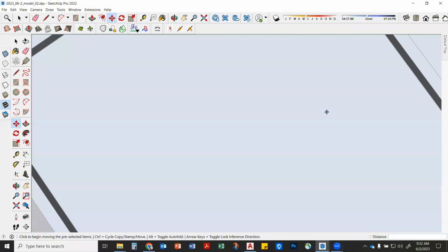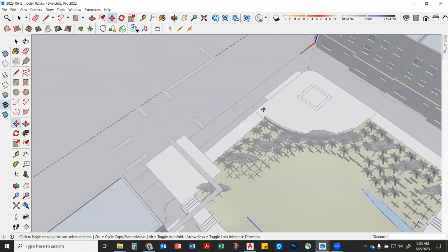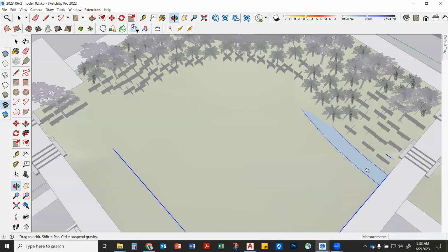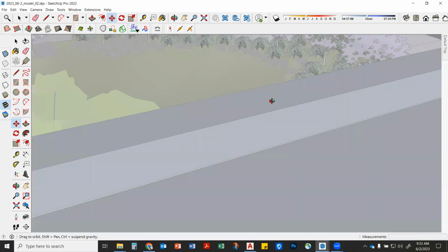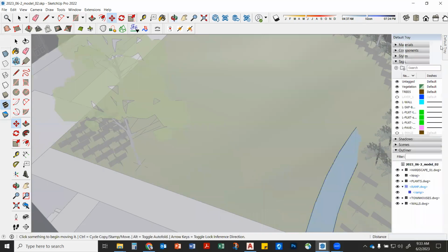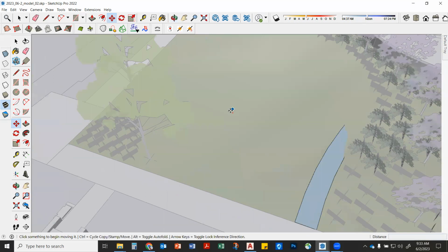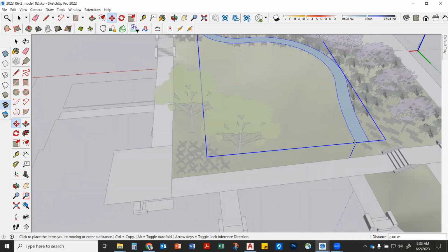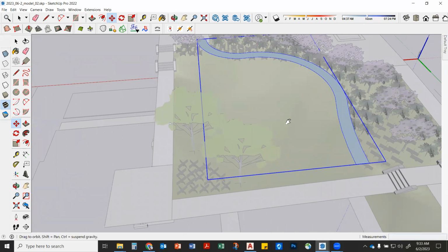And what you could do, if you were just doing a hand graphic and you didn't really care about getting your grading perfectly correct, you could use the drape tool, okay? So we could just move this above the TIN we want to drape it on. I'm going to turn off my townhome so you guys can see this. Okay. So I'm going to move this guy up so it's just above, right? Just like we did with drop GC, right? It's going to drop it down on whatever surface is below us, okay?